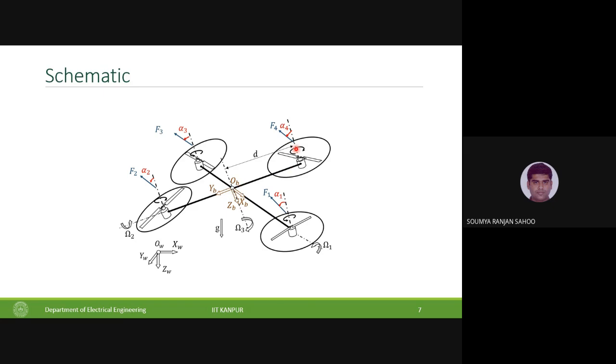Now what will happen in the quad rotor frame? Earlier, in the conventional design, since this angle was essentially zero, the forces could not be resolved in any direction. It is just one component, vertical to the quad rotor frame. But now each force vector can be resolved into a horizontal force and a vertical force with respect to the body frame.